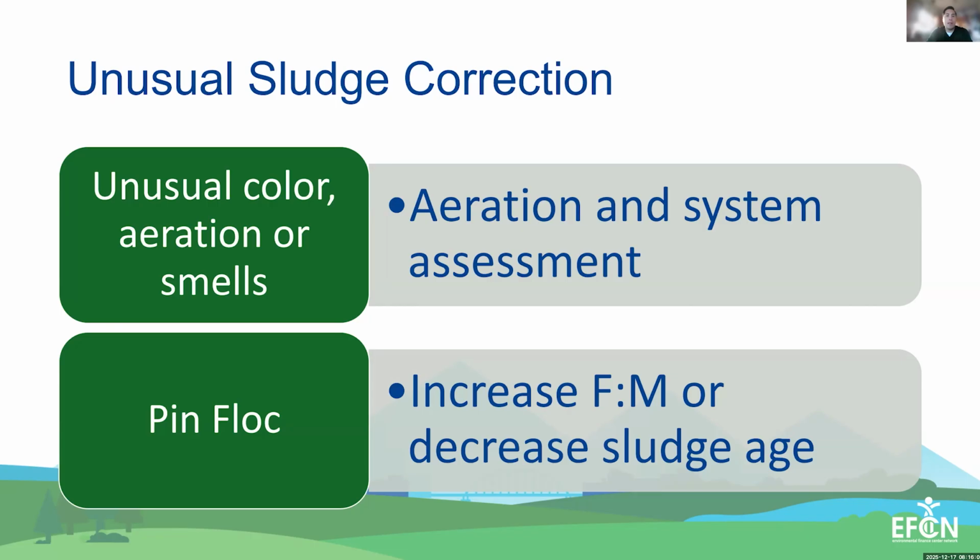Like I said, it can either change the smell of your facility, your activated sludge, or it could discolor it. You could see your sludge darken increasingly. So it could be black or it could be gray. You can see it shocked, so it's white. If that changes from that deep brown color or slightly grayish color that we're looking for, that may indicate some toxic shock. So that's a good visual indicator of when you might have an issue.